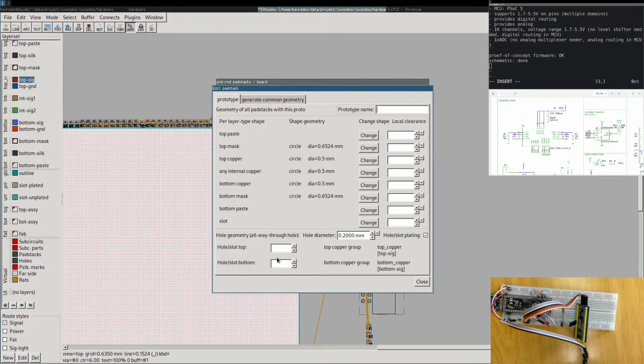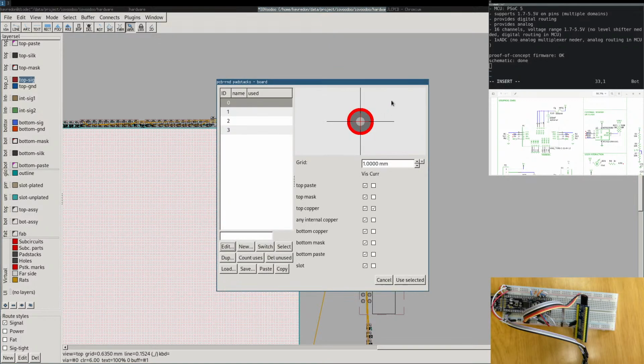Top copper, okay, full geometry, and now we have this, and we also see what it generated, and here we see that it is open. The solder mask is open, so we can have access to the via, and that helps me with probing. For example, with an oscilloscope, I can just touch a via if I cannot touch a pad.